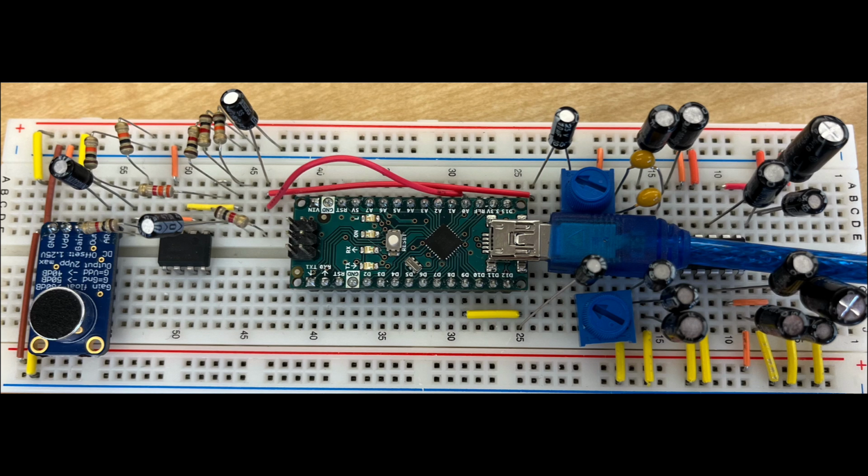Now, the design of the system. The project involves three main circuits. The first circuit handles the initial amplification of the microphone's audio signal. The Max 9814 is used to capture the audio and convert it to an analog signal. Then the LM358 acts as an operational amplifier, or op-amp, that amplifies weak signals, providing gain and conditioning the input signal for further processing. The LM358 output gets sent to the bandpass filter, which isolates the useful frequencies.